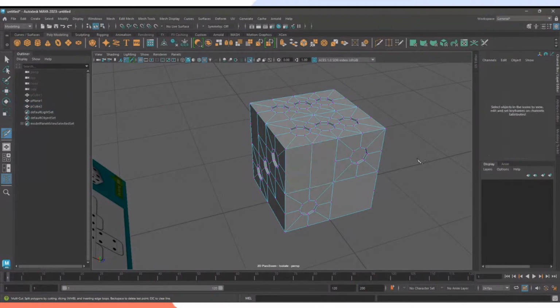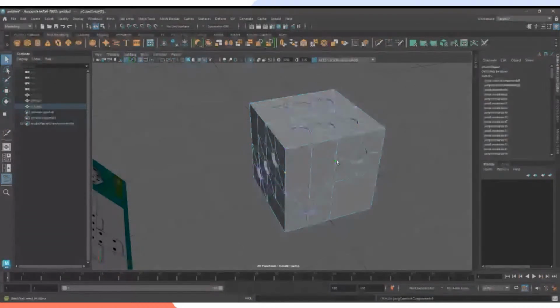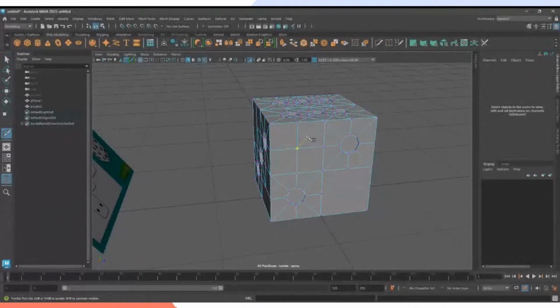Boom, boom. Now, this is just 6 sides, but there's another way. If it's useful, go to Edit Mesh and press Connect. It does that immediately. I don't think this will work if there's already a line here, so it's best to just use the multicut tool. Ching! Now that's fixed. Now that's just 4 sides.